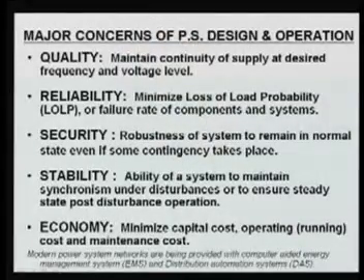But if there is any contingency that is going to come in the near future, what will be the state of your power system? If you are planning in such a fashion that the effect of that contingency will not lead your power system to an abnormal condition, then we can say our power system is secure. However, reliability is related to the probability of outage of equipment. Again, the equipment corresponds to your branches and your power outages, etc.